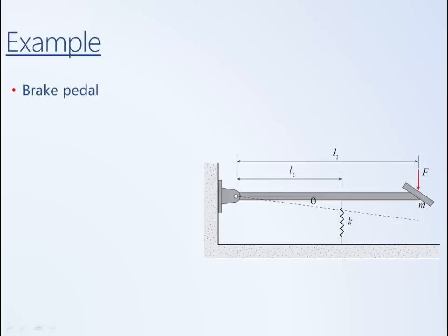With a conventional vehicle, the brake pedal is mechanically connected to the calipers at the wheel, through perhaps a vacuum booster or some hydraulics. But when the driver presses on the pedal, there's mechanical resistance that gives the driver a feel. With a brake-by-wire system, in an electric vehicle, you may want to do braking by running a generator.